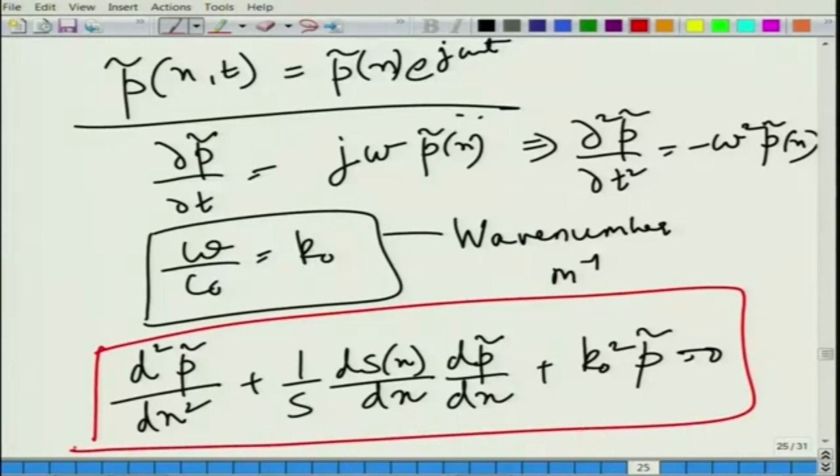So, this then is the Helmholtz equation for the duct with a gradually varying area, and this we can solve for specialized cases. Now, the salient thing to be noted from the star marked equation here is that unless S x is known, we probably cannot solve it.